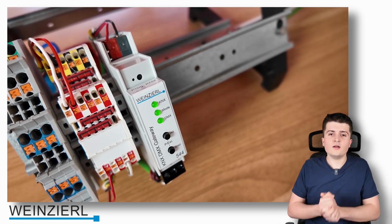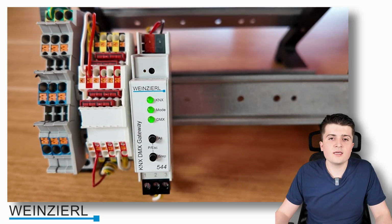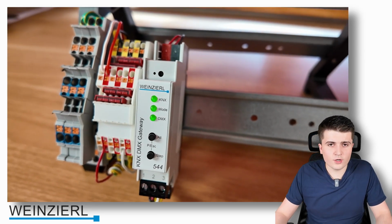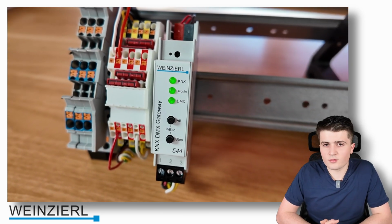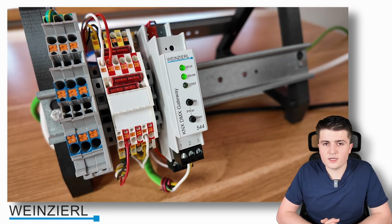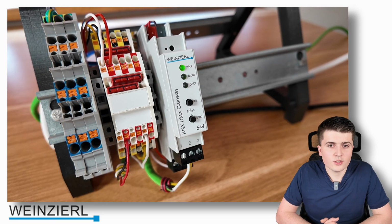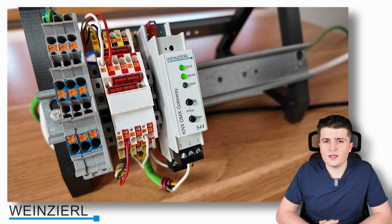Now let's take a look at the hardware of our KNX DMX Gateway. So here you can see the KNX DMX Gateway 544. You can see it's pretty small, only 1 module in total width. And we can see that on the top we have the KNX connection, and on the bottom we have 2 terminal connections. The bottom is for the connection to our DMX line. So here we can see the data connection and also the ground. And the top terminal is then used for the additional 24 volt power supply.